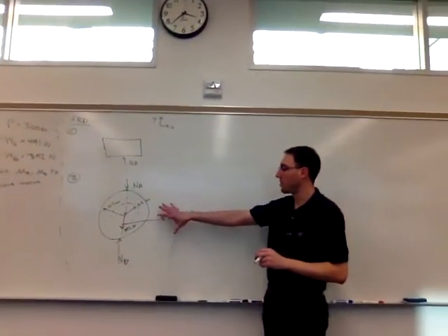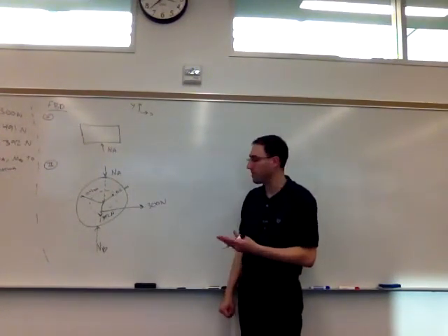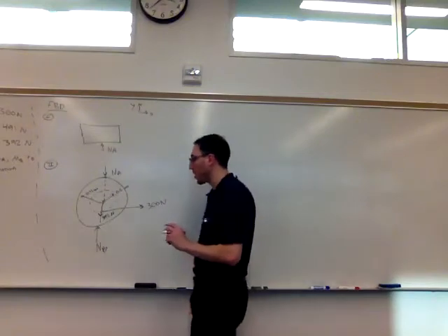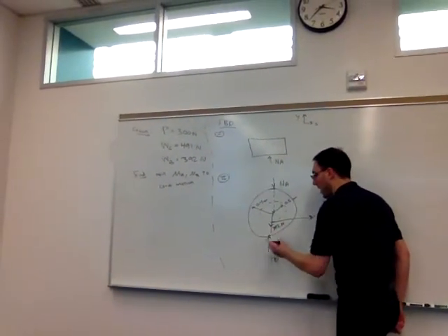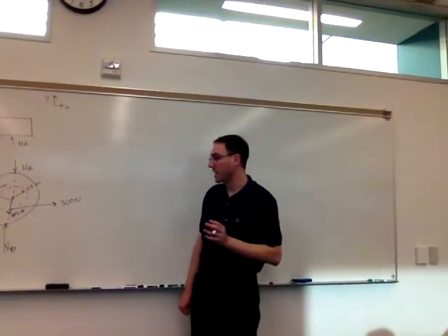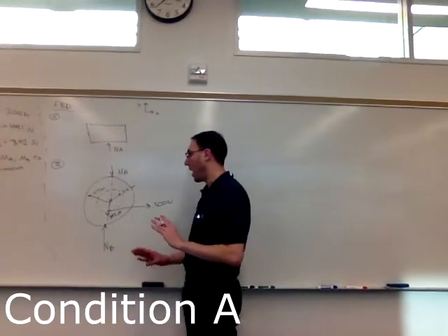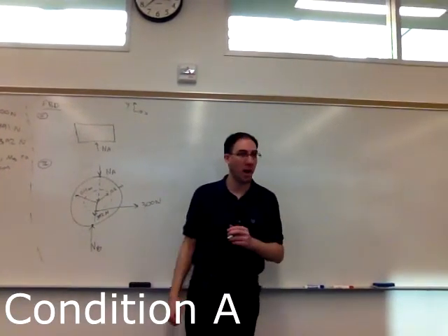Applied force, the two normals, we know the direction of the normals for certain, and we know the direction of the weight. Now we have to think about the friction that it's going to experience at those contact surfaces A and B. Let's start at B. That'll be the easier case. In the first scenario where it's rotating, we think it might rotate counterclockwise.